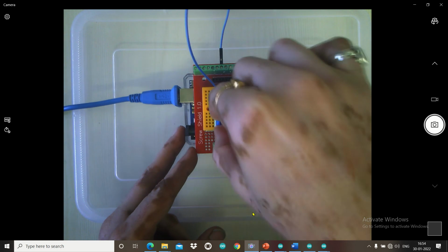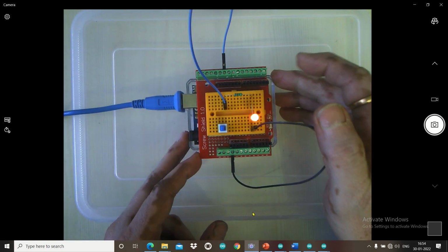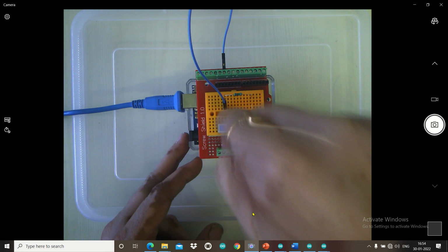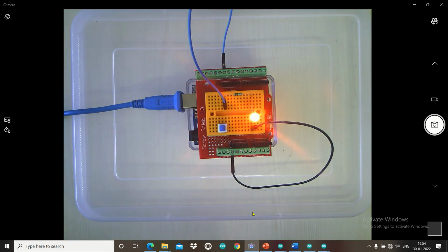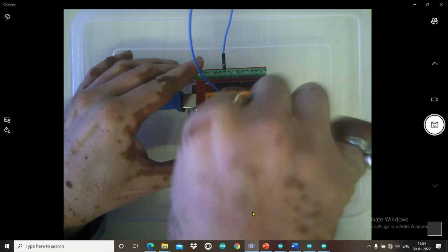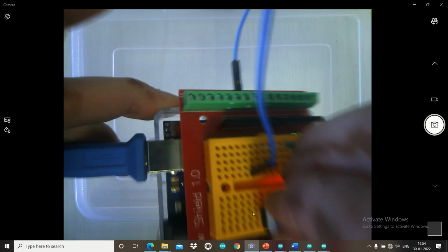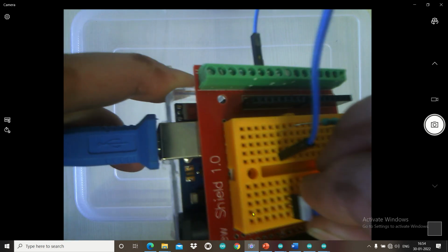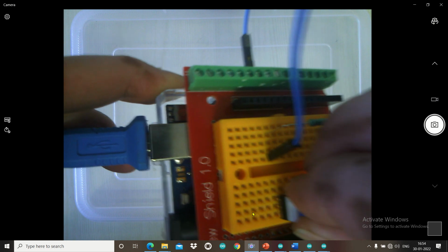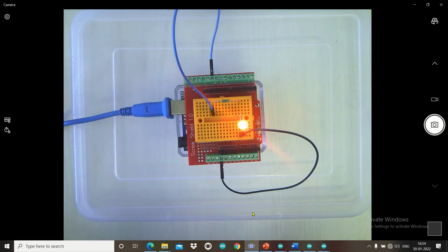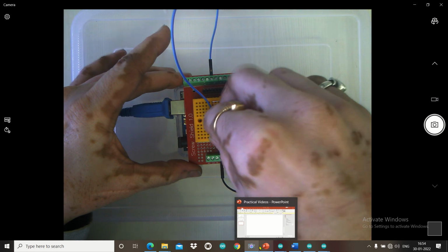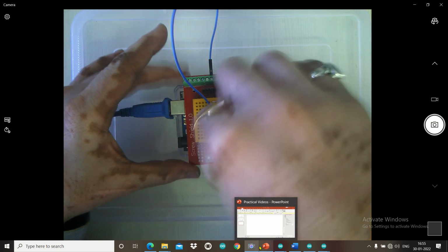While connecting the switch, be very sure that you are not making a short. So here you can see I have connected the switch, and since it is across 3 vertical lines, it is ensured that it is not shorted. Now if I had connected the switch like this, you can see, this means that we are nothing but shorting terminals. Now I'll be connecting the switch like this.